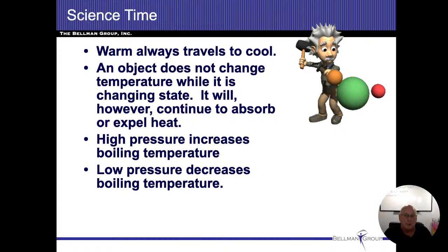All right? But there's still an enormous amount of BTUs that come across. So when we tell people 1 BTU is 1 pound of water, 1 degree Fahrenheit, but when we go from 210 to 214, that's not 4 BTUs. That's more like about 1,000 BTUs.